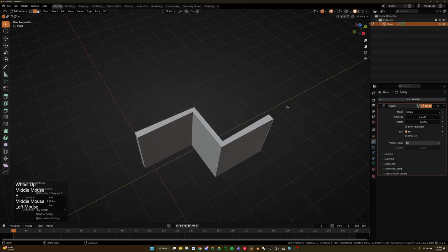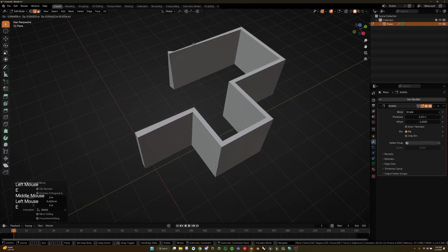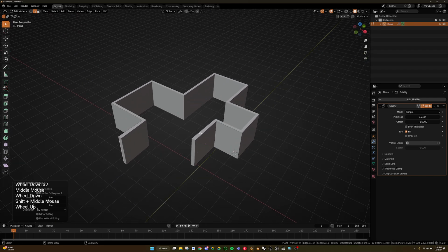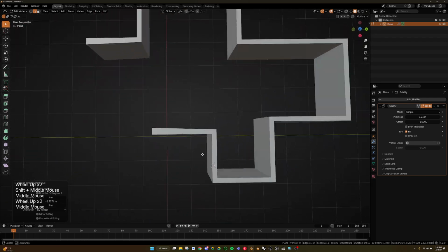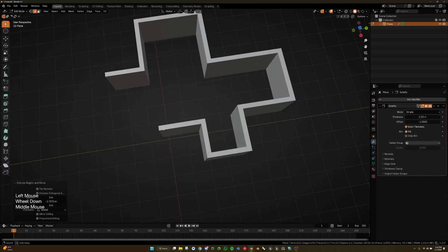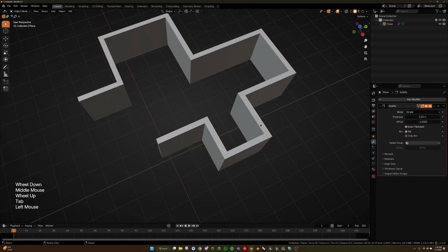And you can do things like this, right? You can make walls like that really fast. Once you get used to the program, it should be more fluid for you. But you can see the walls are not really aligning, so even thickness fixes that. And then you can say, oh, I want my walls to be 8 inches. So you can click in here and do 8 inches.